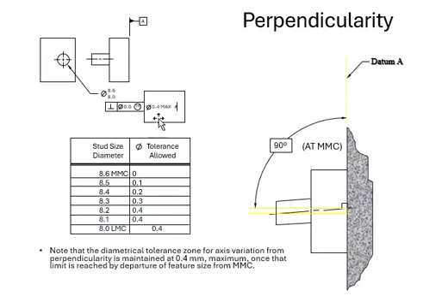And don't go beyond 4 because your max is 0.4, so you don't count it up to 0.5. When it goes from 8.2 to 8.1, you still count the same, 0.4. It can't go anything more than that. The same thing is true when you approach 8.0, where you get to the least material condition. Your max and your least is right there. Okay. So that's how you fill up your tolerance allowance when you deal with a 0.0 tolerance zone. You can go all the way to max. You're going to increase each unit coming out from the max, which is this upper limit, towards your lower limit, which is your 8.0 in this example.